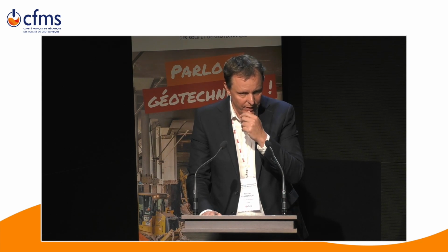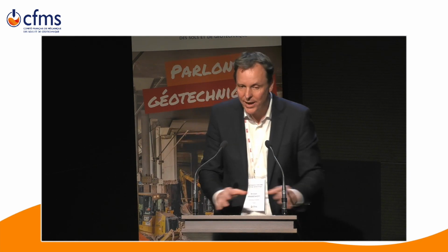We had a lot of discussions about that. There's this concept of extension elements where you can extend the stress field to infinity. That is a possibility. It's something that complicates things, in terms of modeling, without really providing much gain. So what we say now is the same as conventional finite element analysis: make the domain large enough. And that means, of course, strictly speaking, it is not a lower bound if that's what you're doing. But experience shows that that approach works just fine.